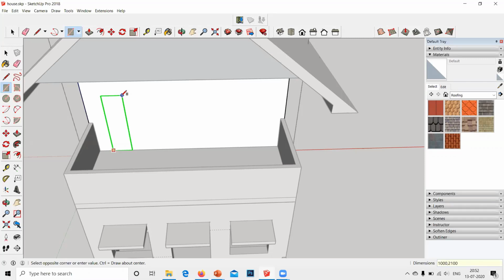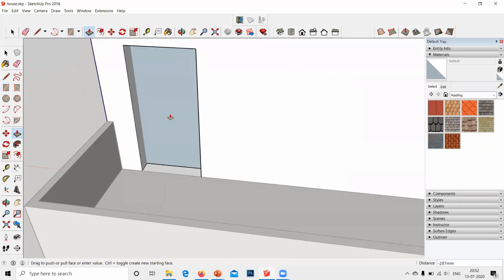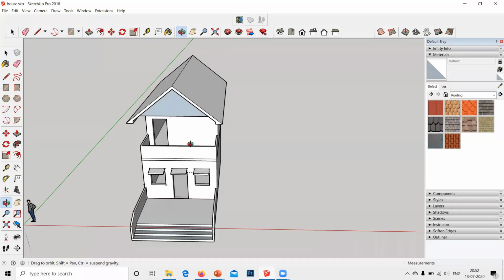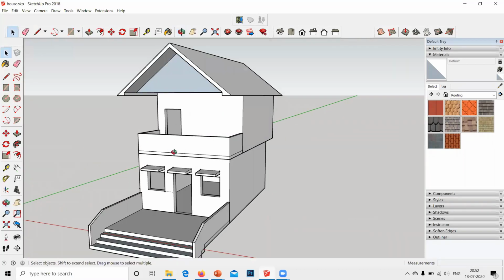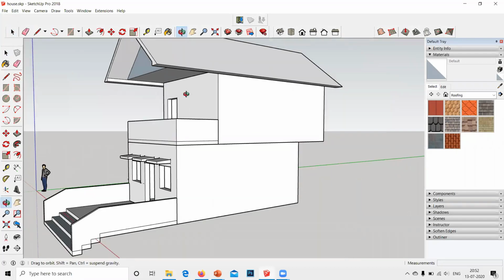Comma, to give it a height. Click enter. A height of 150. I did this with the control option to get a height. Okay, we are having a door to our balcony. Once this is complete, you don't have to do more. I want a chhaja over it. Create it because we already have this thing as a component.